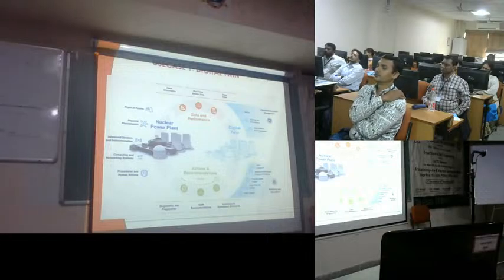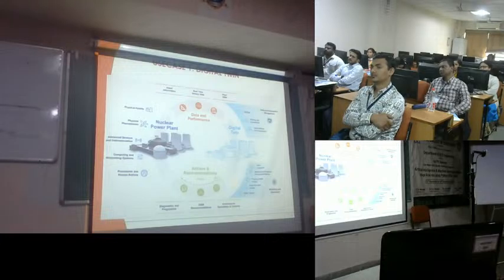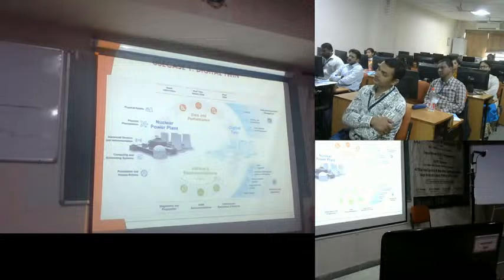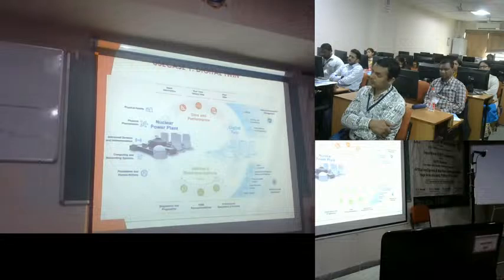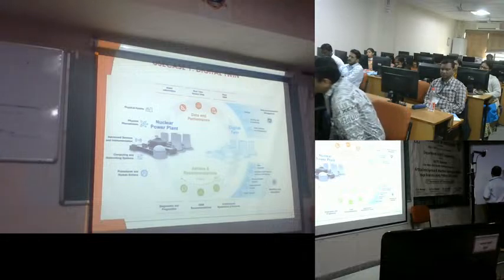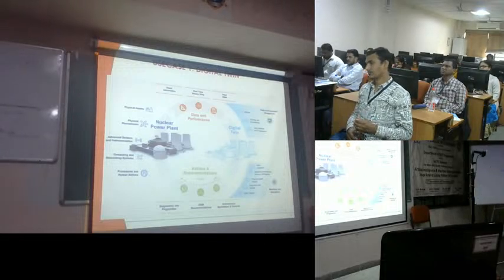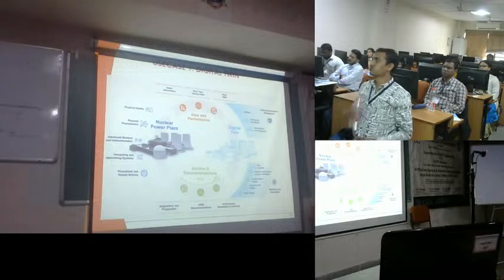and we need to monitor the healthiness of these components, because the malfunction of any component may deviate your process, and which may be hazardous, right? So various sensors are there, which give the healthiness of your particular physical entity. For example, whether your valve is closed or open. So there will be a sensor which is known as a limit switch. In the limit switch position, it will automatically find whether it is open or closed, because many times the valve needs to be closed. It may be a requirement of my process, and which is not actually, right?